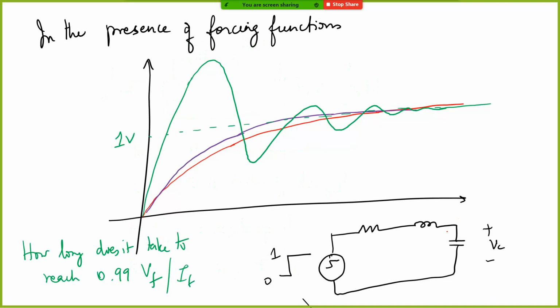So even when you talk about an underdamped response, if you take this underdamped response that I have drawn, you will see the energy transfer happening between the inductor and capacitor. Only thing is the envelope will go down. If your capacitor voltage is going up, it means that energy is being stored in the capacitor and energy is also getting dissipated.